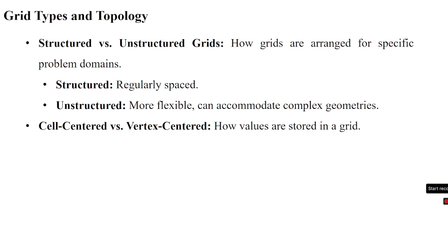Because whatever shapes we have, suppose aerofoil shapes, it is not always possible to have a structured grid. So there is always an unstructured mesh, maybe with triangular mesh at this location, square or quad elements at this location, and prism elements at the corners along the border of the geometry.